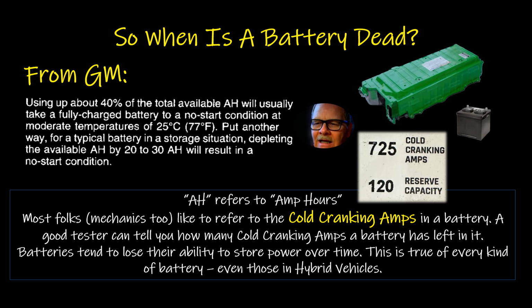So AH refers to amp hours. Most folks, mechanics too, like to refer to the cold cranking amps. That's the big deal now. Years ago, nobody talked about cold cranking amps, but now they do. And it's good. You can buy from Harbor Freight a cheap little handheld tester to test for cold cranking amps. It's a little bit annoying to use, but I bought one just to play with, and then I gave it away. But in other words, it'll tell you how many cold cranking amps the battery has left.